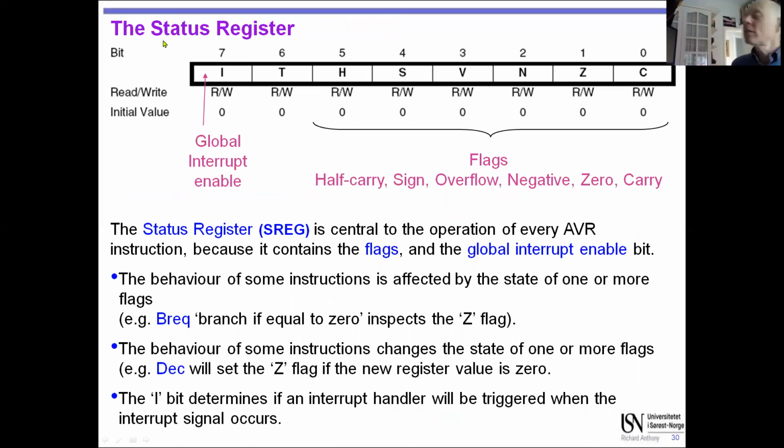Richard, can I just add one thing? Yep. You have to have a look into 2's complement and also compare it to 1's complement. 1's complement has 2 zeros, a +0 and a -0, and then you have the +127 to -127. But in the 2's complement, as Richard was explaining, you have only 1 zero, and you go from -128 to +127. So there's a difference between 1's complement and 2's complement, and you can imagine, because in 2's complement you're not having 2 zeros, you're much more efficient in your numbering.